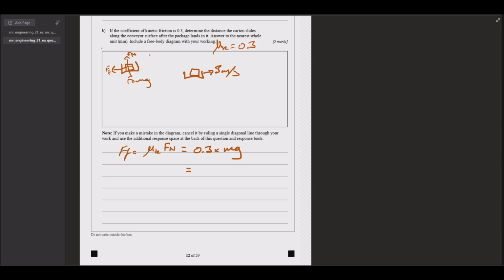And the mass is going to be the combined mass of the system, so 2.25 times gravity times 0.3, and that friction force is 6.62 newtons. We convert that to acceleration because we're going to use it in our SUVAT equation. So divided by mass. So actually, I didn't need to put that in. But you know, oh well. Acceleration is 2.94 meters per second squared.